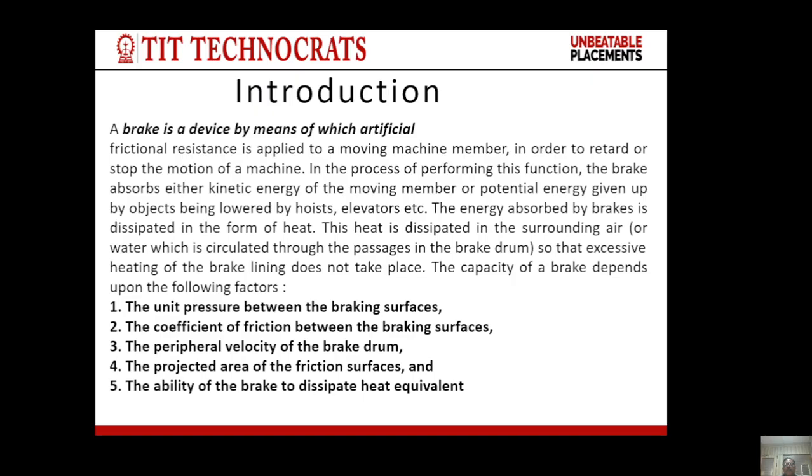This heat is dissipated in the surrounding air or water which is circulated through the passages in the brake drum, so that excessive heating of the brake lining does not take place. The capacity of a brake depends upon the following factors: the unit pressure between the braking surfaces, the coefficient of friction between the braking surfaces, the peripheral velocity of the brake drum, the projected area of the friction surface, and the ability of the brake to dissipate heat equivalent.